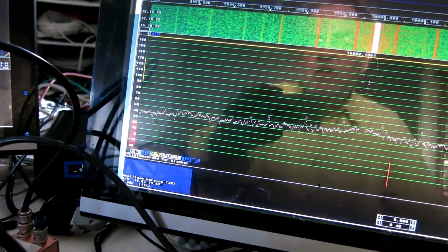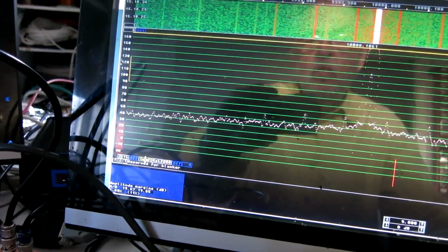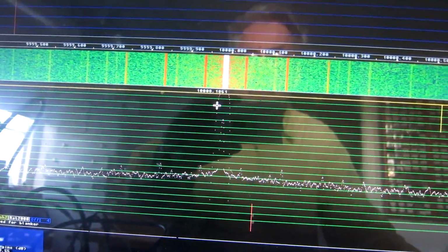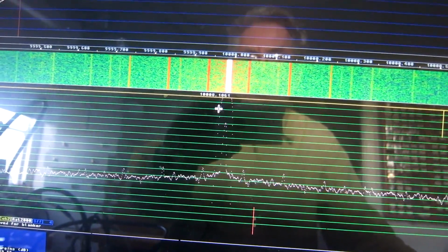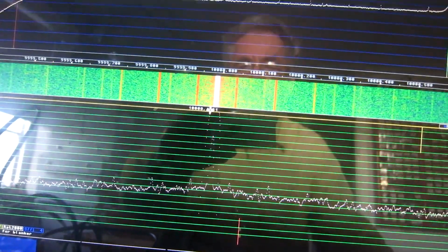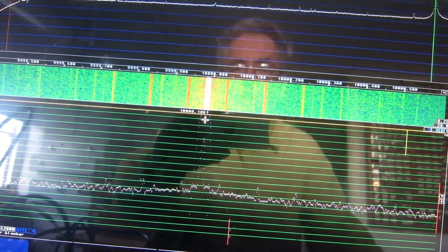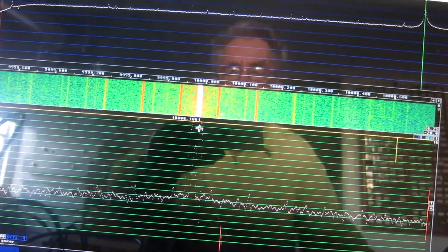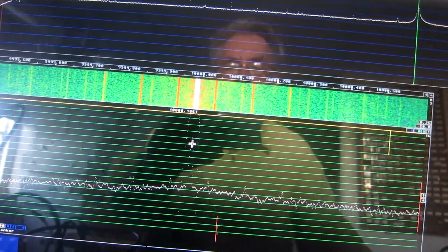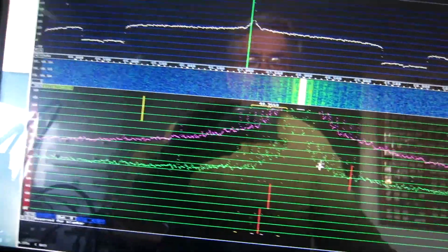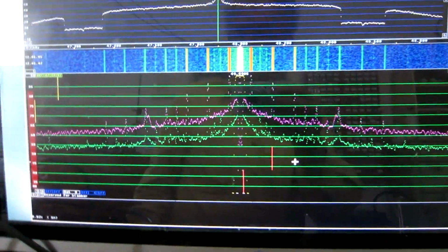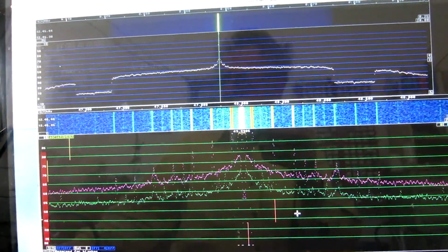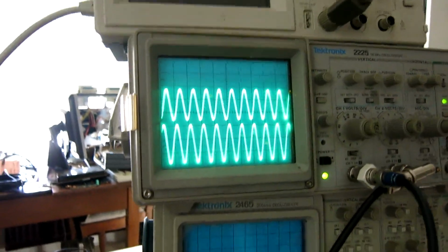And then I look at what is sent to the network in the mode coherent 2, where the carrier within this narrow filter here is used as a reference phase to detect AM and phase modulation, or rather I and Q signals with respect to this carrier. And that is sent to this instance of Linrad. What I have on the screen is this, and I turn the fine adjustment knob on the phase. It looks here on the balance like this.